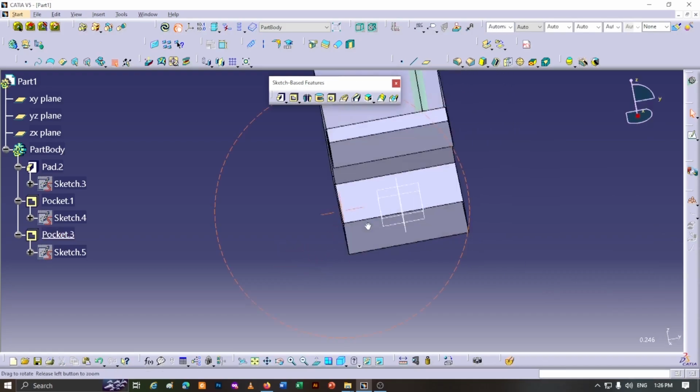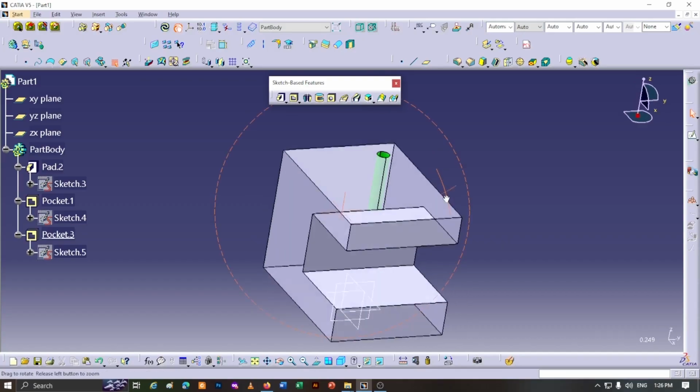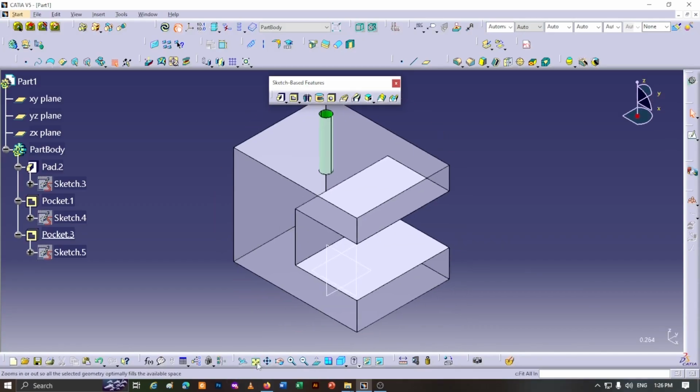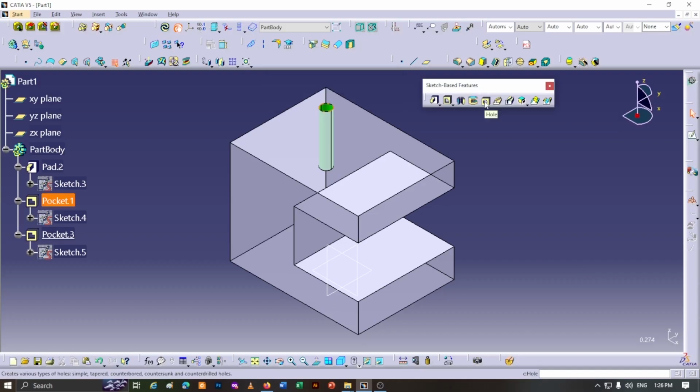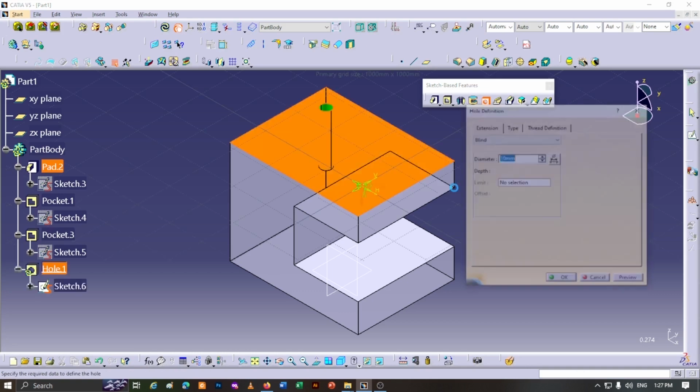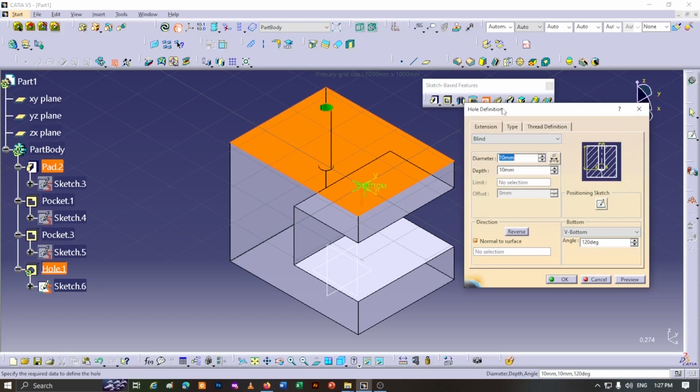I set the view to isometric. I click on the Fit-Align tool to have an appropriate zoom. I activate the Hole command. I click on the top surface where the groove exists. The Hole definition window opens. A preview of the hole is also shown. I click the V symbol next to Blind. I select the Up to Next option.